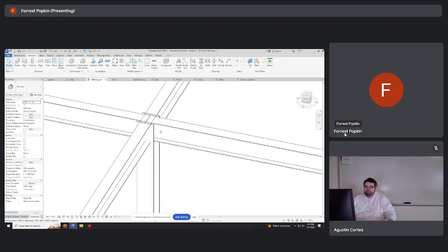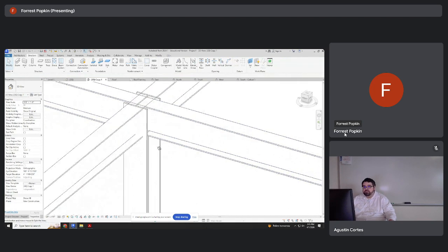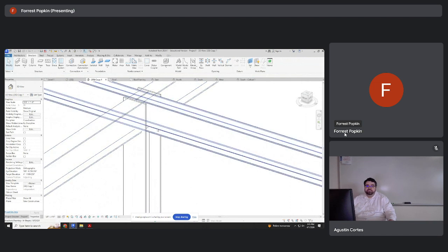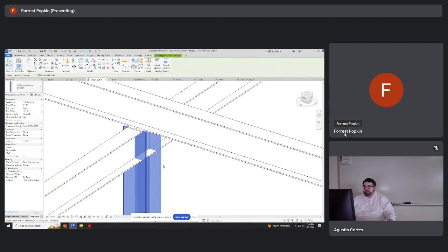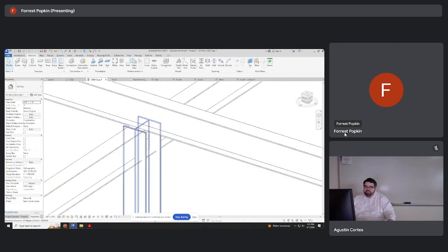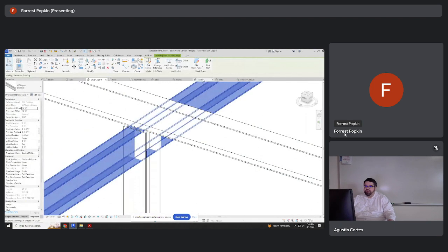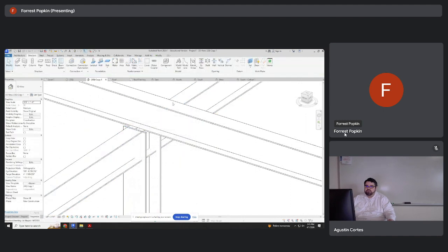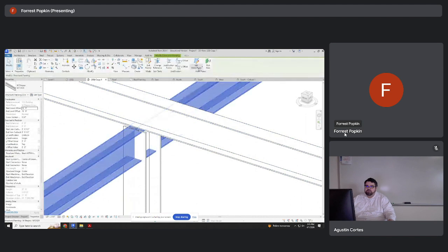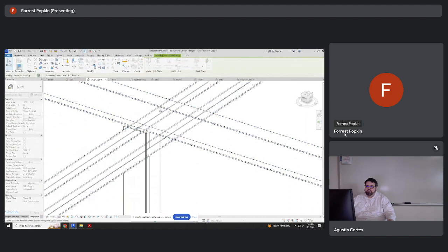So now you're starting to see it looks like a complicated sandwich of a bunch of different things. And in practical, like I said, reality, what would happen was this would be like a -1. And you'll see it's associated now with the top of that, this beam. So I'm still not in my right area. So I go back to edit work plane, and I can actually go to the top option, which was pick new.